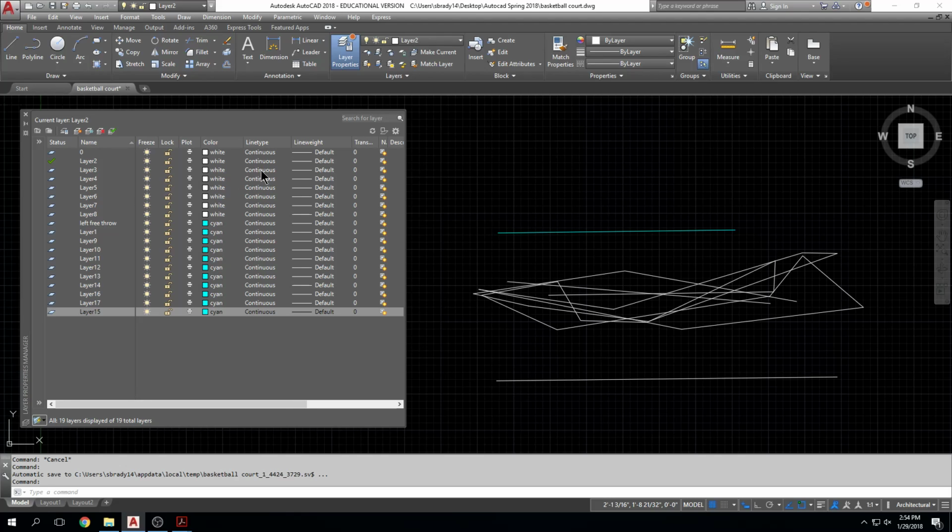One of the things to know is that different line types mean different things in AutoCAD. If I draw a line with a dash in it, it could represent something above me. We're looking at a floor plan, but a dash line might mean there's a projector above that area. A dash line can also mean demolition. So you have a floor plan, but a couple of the walls are dashed. That means they're subject to demo. So line types mean things as you're drafting in AutoCAD.